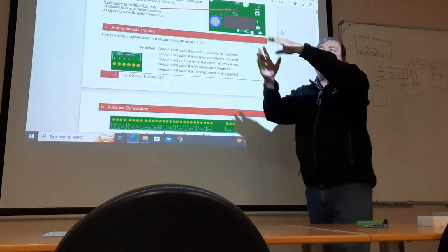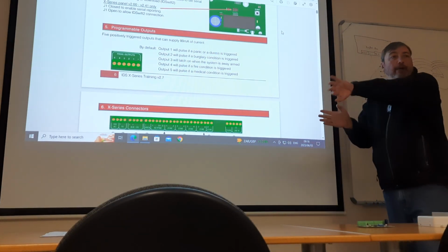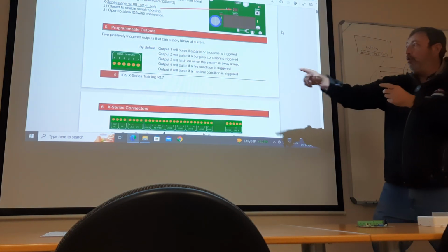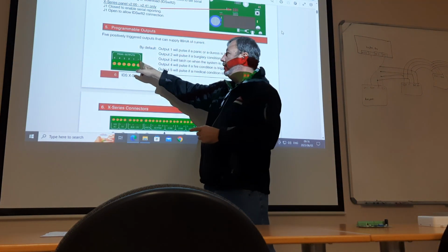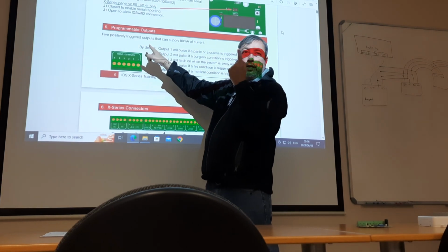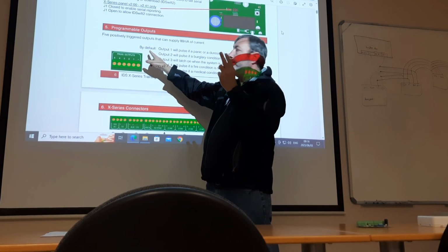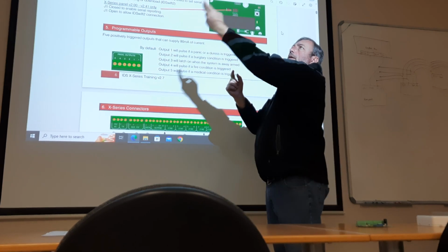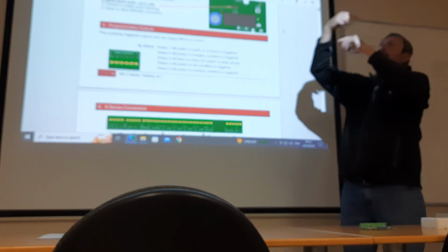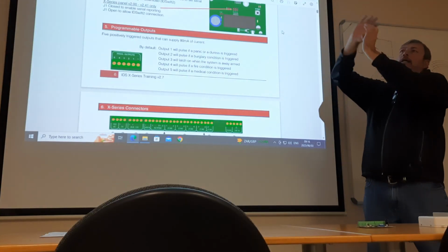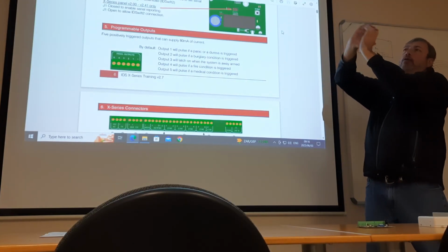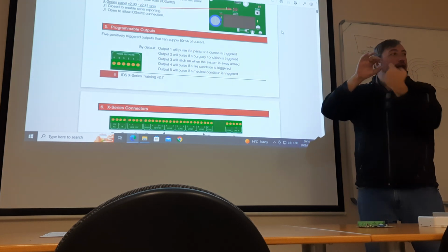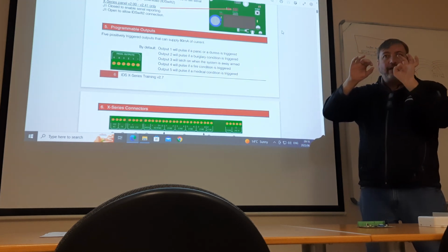So by your main entrance, where the keypad is on the inside, the negative will be connected to the negative of the LED, and the positive will go to output number 3. They take the wires and drill a hole through the wall, and on the outside they take a piece of PVC pipe and put the LED in there. You know, one of those big ones.